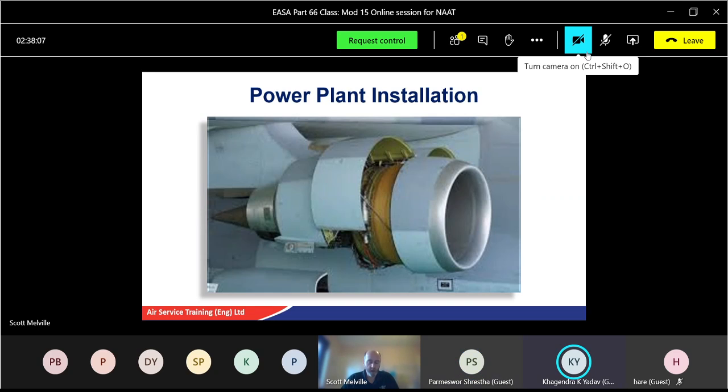There's a lot more goes on at 95, but that's the basic one you want to remember. And 110%? If it exceeds 110% RPM, the APU will switch off. Good. That's the three basics, but at 95% you've got a bit more: your hour meter starts, your generator light, buzzer, ignition off, three-way pneumatic valve and that sort of thing. But if you remember the three basic ones for 35, 95, 110, you're pretty much halfway there.